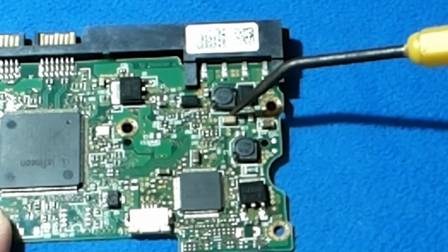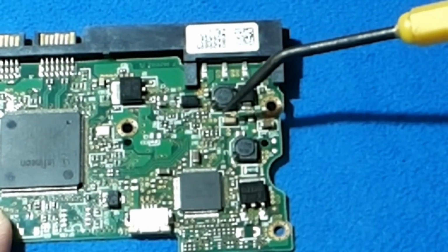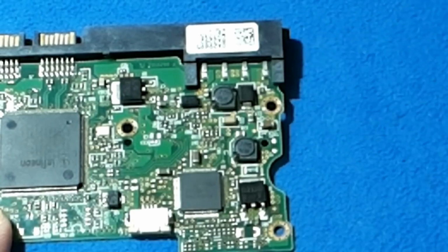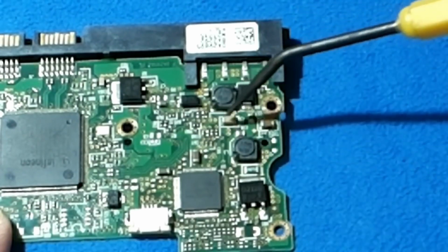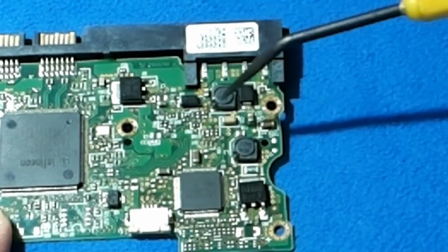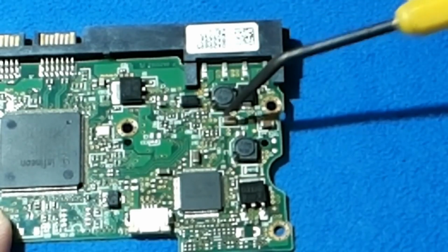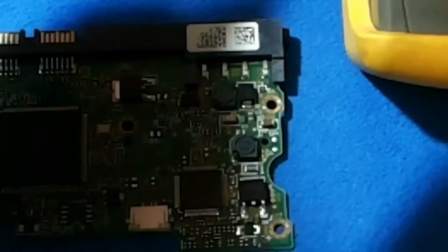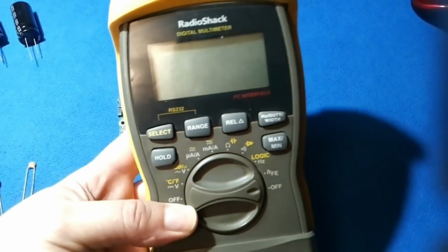Capacitors with high capacitance can fail by becoming short-circuited, which adversely affects their operation within the circuit board. Such failures may lead to significant issues in electronic devices. Using a multimeter in continuity mode enables users to detect short circuits effectively, indicated by a beep when continuity is established. This function aids in identifying problematic capacitors within a circuit.